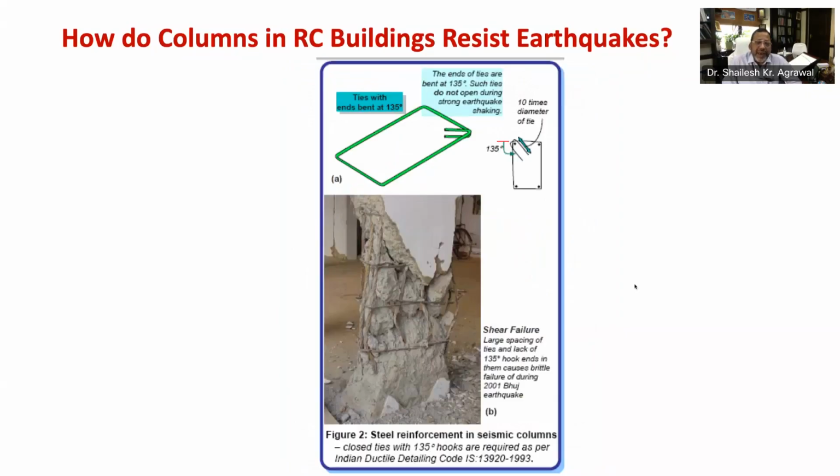The first is axial flexure failure, also known as compression bending failure, which means buckling or crushing of columns. Next is shear failure, which is shown in this figure 2b. Shear failure is brittle and must be avoided in columns by providing transverse ties at closer spacing. Based on these failures likely to occur during the shaking, let's discuss the design strategy for columns.